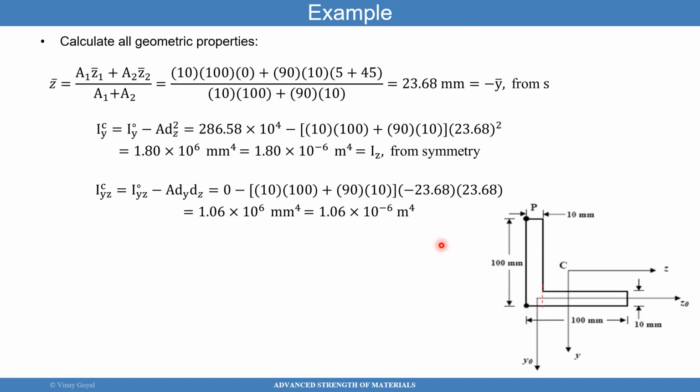So that's 0. And then I have to calculate where the centroid of this little piece is, and that's about here. So let's see if we can calculate that location. You can see that if this is 100, that's 10. Therefore, this distance here is 90. And 90 divided by 2 is 45, which is the height that we're looking for.